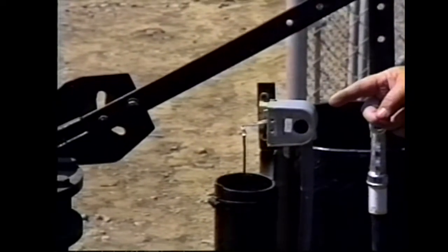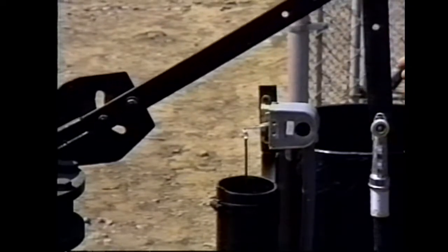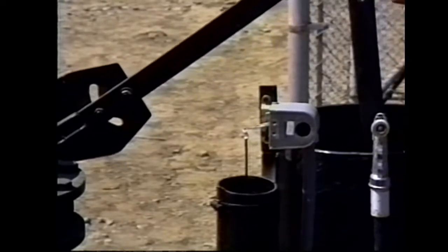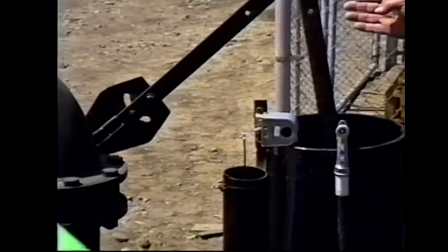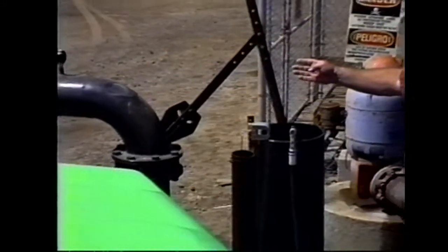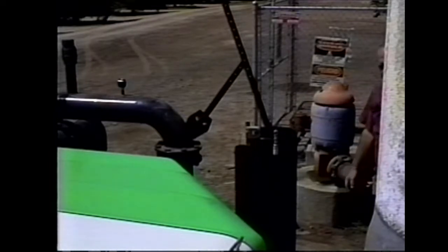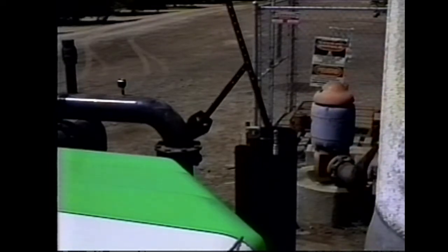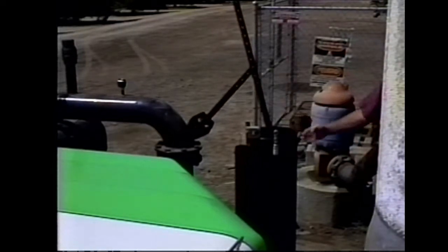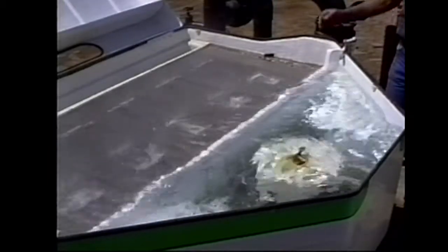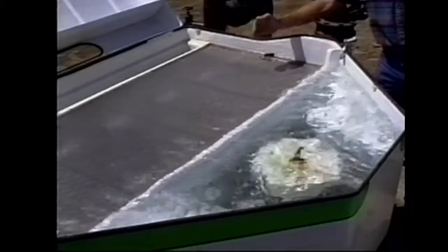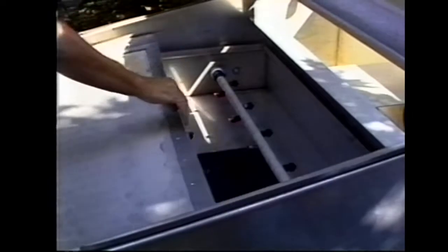In some undesirable situations, the water supply sometimes decreases with time. Installers must then place a float-operated butterfly valve on the booster pump discharge. This should be avoided whenever possible because the irrigation system distribution uniformity drops when the pressure is lowered. The screen is kept clean by the vibration of the water on the screen itself, plus by rotating spray wands under the screen.